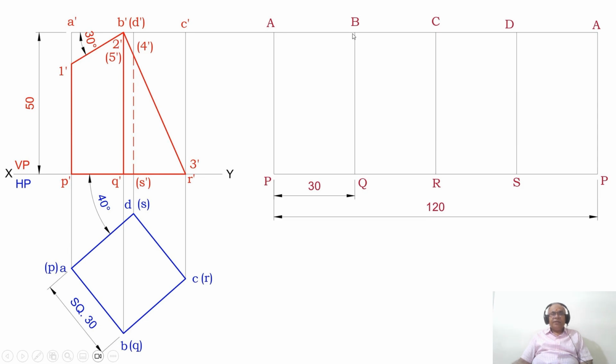Then after B, you have CR. So BC, you don't have a section plane. So I want to consider CR. Yes, CR is at this point. So you are going to get 3 dash. After that, you are going to have D dash, S dash. Yes, DS. So D dash is invisible, S dash is invisible. Invisible to invisible is invisible. So the 4 dash will be in bracket.